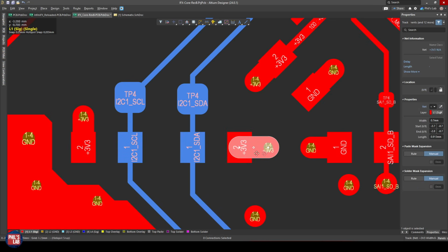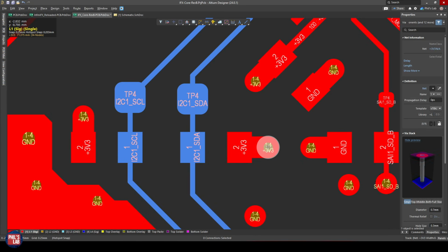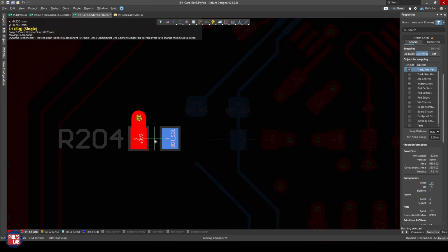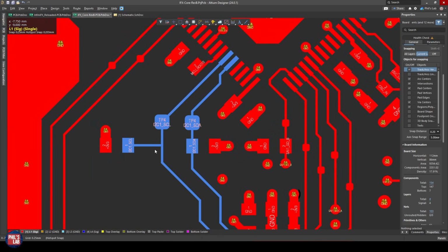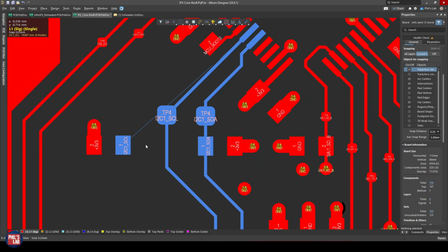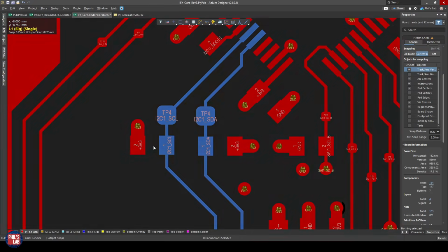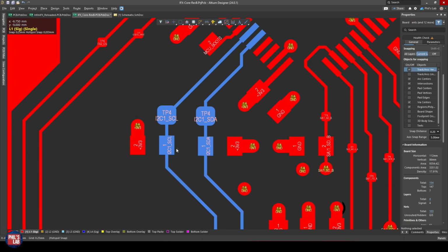I'm routing through with the clock and data lines, but on the other side, the pull-ups to my system level VDD voltage, I have short white traces with a via going to a power pour, which is on the opposite side of the board. What I could also do is move my pull-up resistor like so, connect my clock line like this, and then do this kind of stub routing, but this is definitely not what we want. Although for I2C this probably won't make much of a difference, the ideal routing is through the pull-up resistors rather than having these little branches and these little stubs.